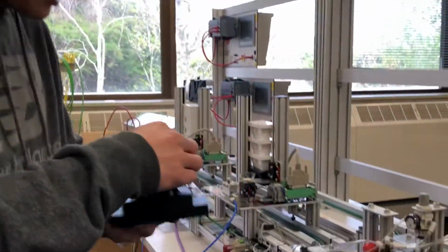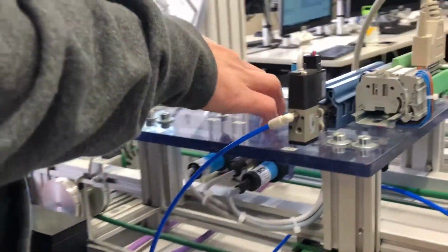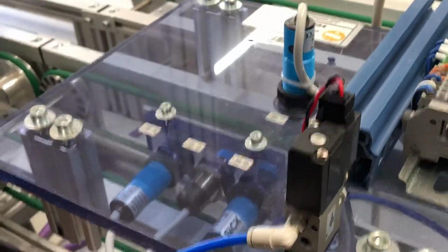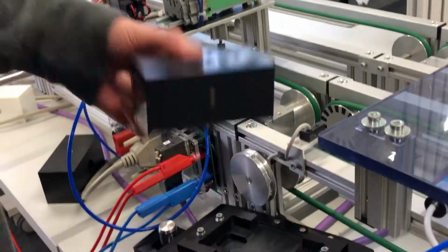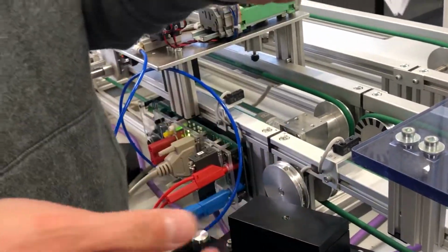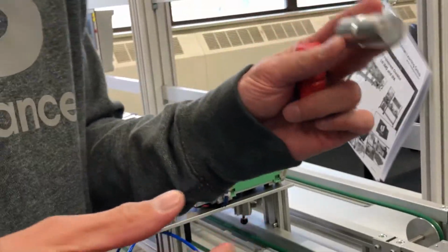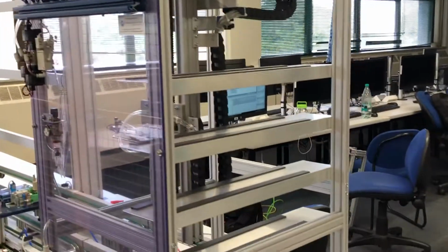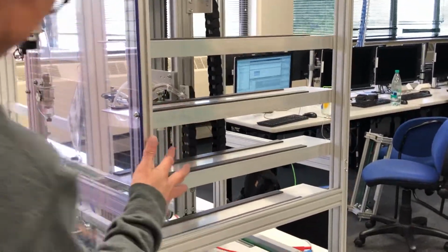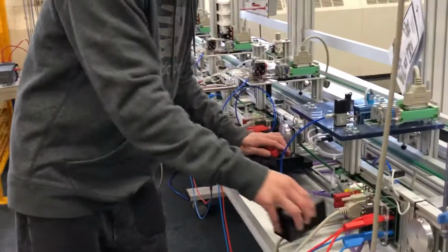And then the pallet will move to station 4, where we have some sensors here that can recognize different colors and different materials of the middle part. So we've got 2 different colors, the white one and the black, and for the material, we've got plastic and metal for the middle part. After sensing the color and material, station 4 will send a signal to station 5, the racking system. You can see you've got 4 different racks here. It means we can put up to 4 different products.